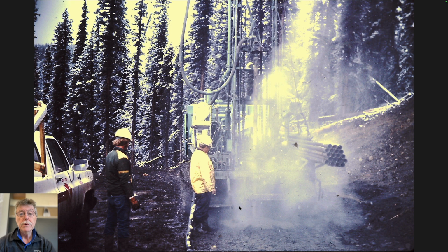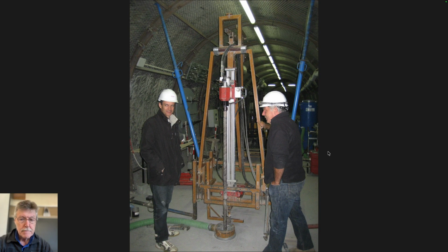If you don't have to drill with water, and you can get away with drilling with air flush or with foam, it's much easier because you don't have to resupply a water truck to be able to pump it down the hole. You never get 100% return, so you have to bring another truckload of water in to continue. This is the drill steel here, which has slightly larger flanges on the end so it can go into the next male thread that gets put on there.